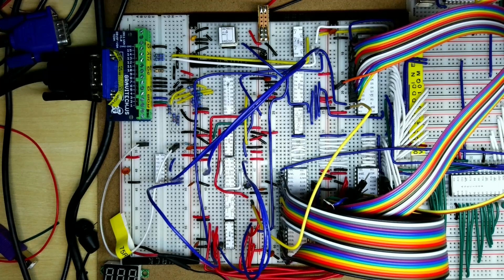In the next video, we're going to be doing quite a major rework of the video controller, in that we're going to be swapping out the large video RAM chip here, and replacing it with 2 slightly smaller physical chips, but they've actually got about 16 times as much memory. This is going to allow us to have 16 foreground and background colors by character, and in the future will also allow us to do some higher resolution graphics.